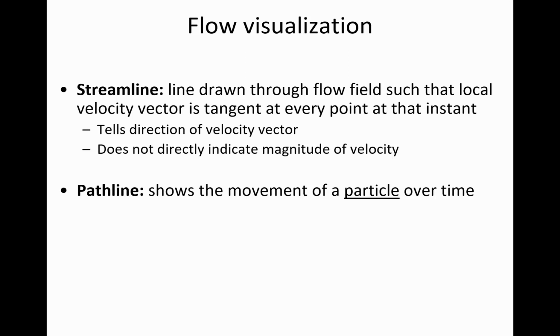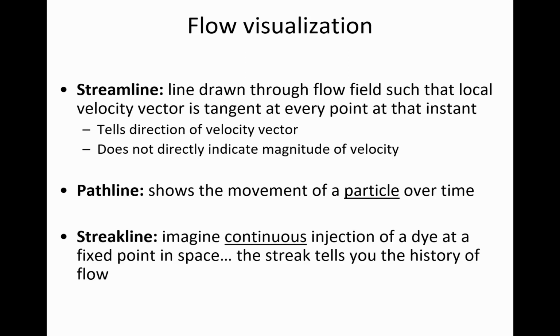That path line would show you how the particle is moving over a period and how far apart the particle is moving, like let's say for example every 1 second. If it's moving a big distance in those 1 second intervals, then that would give you an indicator that the velocity was high. And so that's what a path line is.